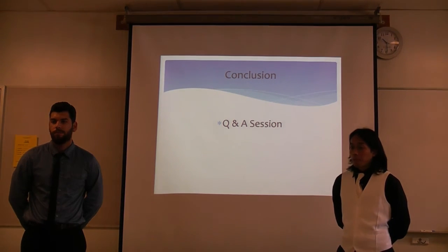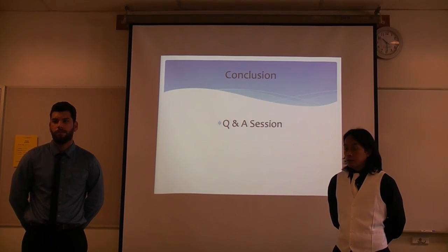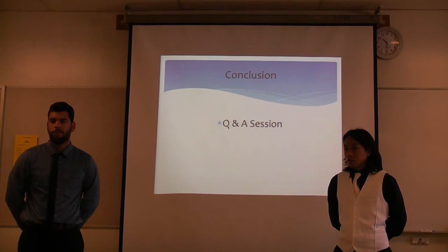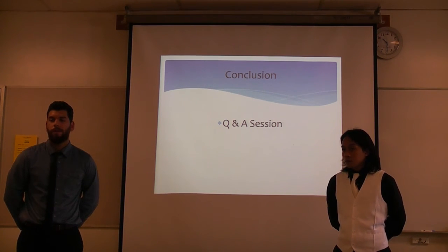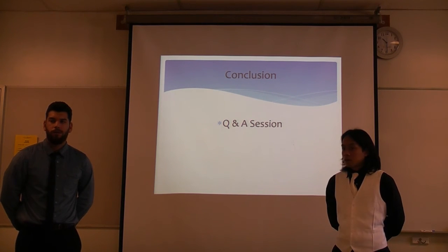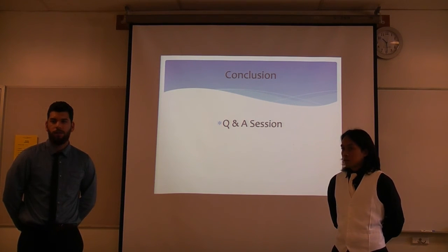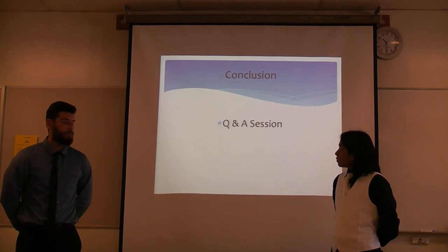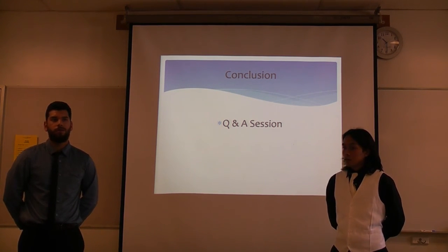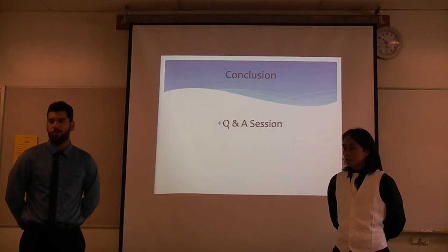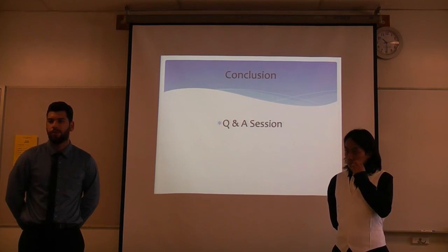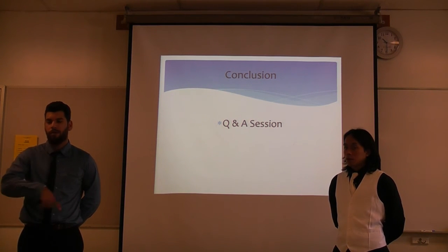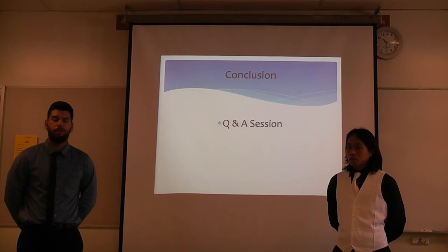So for your future enhancement for your barrel shifter, you had a destination register. Does that mean when it passes through the barrel shifter, it goes back to the register file? It would have been in parallel, so it would have acted just like the ALU in the IDP. The destination register would have been the same value that would be stored if it were being used in the ALU. So yes, it would just reroute and go back into it.